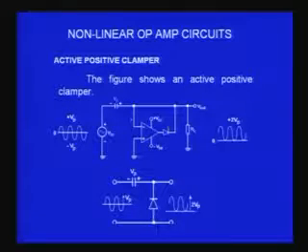So therefore I have used here an active diode, which is an op amp with the diode connected as in the previous example, and if you look at this as an ideal diode, this is my capacitor, the circuit is very similar to this, the RL is what I have at the output load resistor. So this is the input signal.